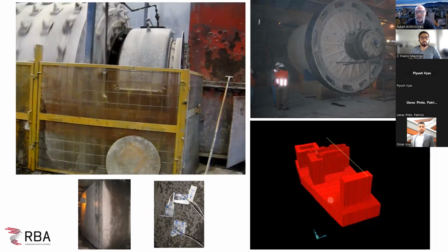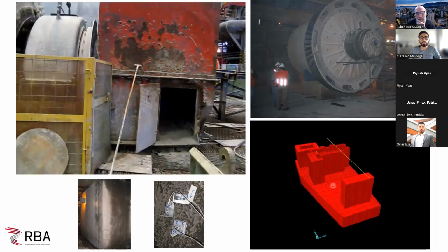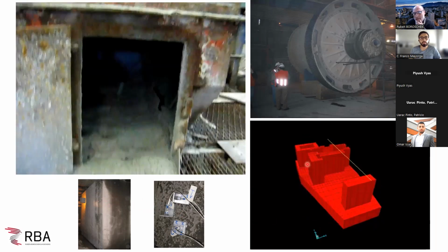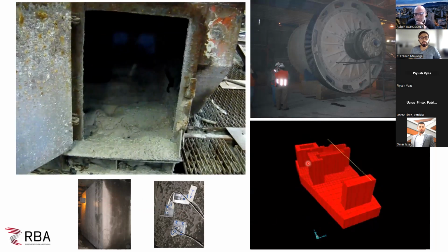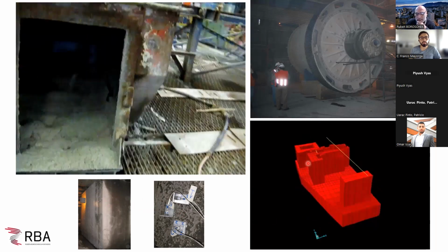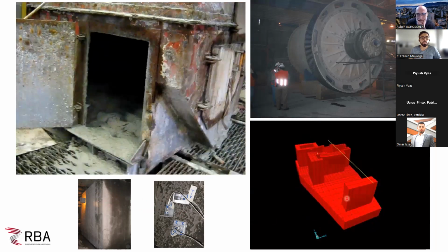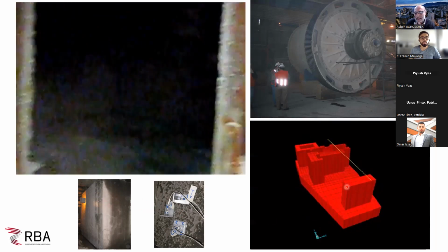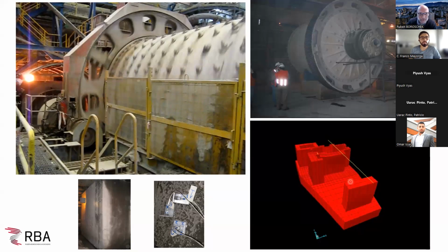And what we do is try to model the thing, understand the behavior, and recommend retrofit techniques based on some type of model updating, but very crude model updating that relates to deformations and some of the dynamic properties, but mainly stiffness related monitoring. So this is quite common.